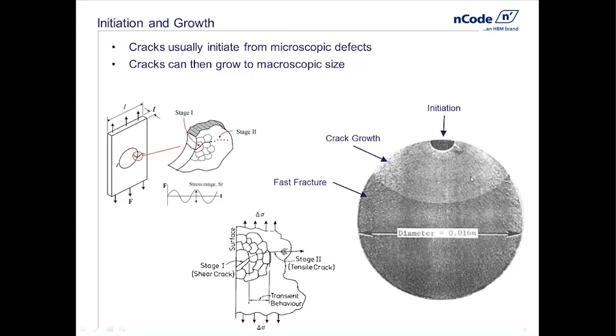Crack started here, and you can see, might be hard in these pictures, but you've probably seen in fatigue specimens before, these things called beach marks. What these are is essentially how much the crack grew each time, just like the waves approaching with the tide coming up the beach.